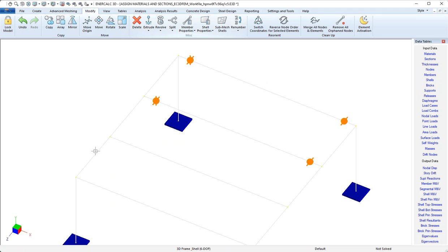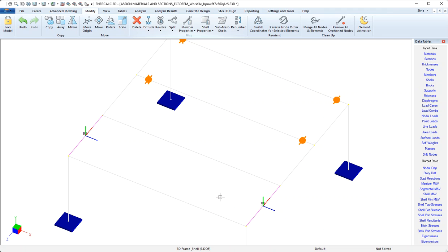The other thing to keep in mind is that the girders in this model are actually 3 analytical members each. So we need to be a little bit careful if we want to pin the connection ends of the girder. We need to make sure that we understand what's the starting end and what's the ending end, and that we assign those fixities to the correct members. In this case, I've found that the two that I've selected both start at the column and are drawn toward the other column. So these would both be candidates for a start end release.